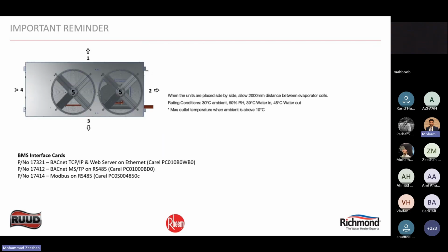On the space, we understand a lot of times you want to save space. There are constraints across the board. However, certain requirements are mandated by us. There are some exceptions that we follow depending on the sites and design. However, as a standard, we suggest that there should be at least 1 meter to 0.85 meter of clearances across the heat pumps, for the sake of serviceability, also to ensure the airway path is not blocked. So we recommend this.